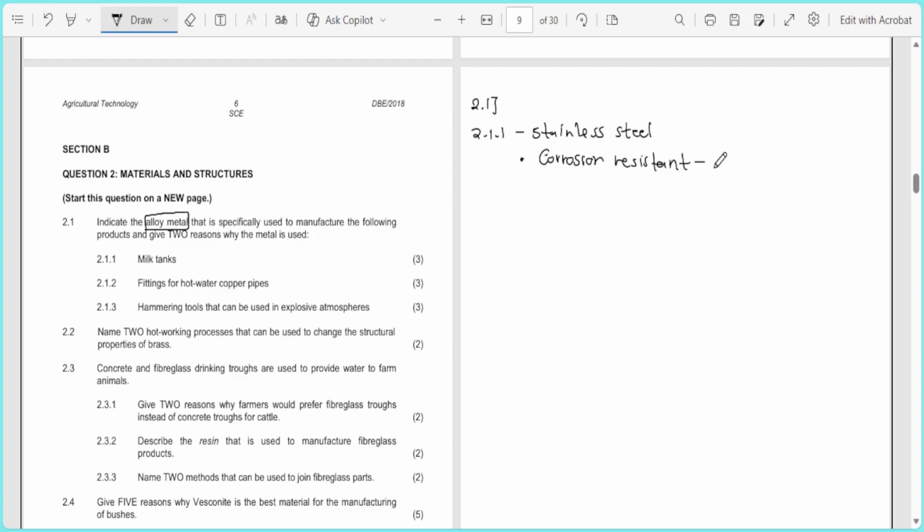Using stainless steel is going to be a better option, because the chromium contained actually forms a passive oxide layer that prevents rust and chemical attacks that come from the chemical sterilizers. So the reason why we are opting for stainless steel is because of its corrosion resistance.